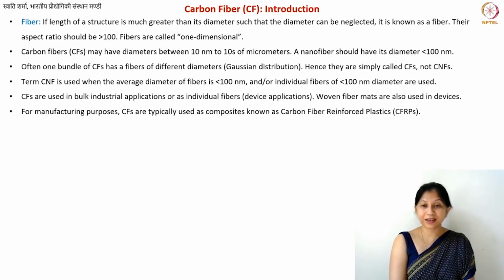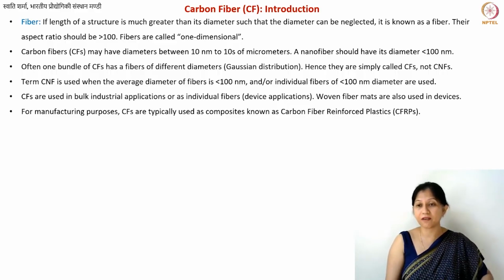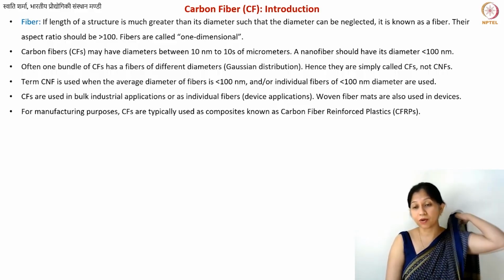And why do we need the resin? In most cases, when you are doing this weaving of carbon fibers, you need some sort of lubricant. It's easier. Otherwise, you may end up damaging the surface of the fibers. You may even end up breaking a lot of fibers, because they are, after all, made of carbon. They are hard and brittle. But once you have a lubricant, once you have a resin, then the weaving is easier. And that is why we often use these resins.